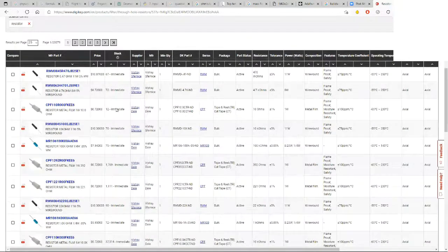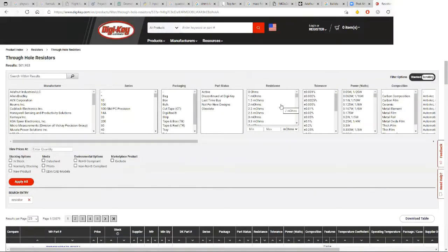Now, here we are. We have all sorts of resistors, but we don't need just any resistor. We want, let's say, a 1 kilo ohm resistor, or so we can type in this resistance box. What value of resistance are we interested in? We want something between 1 and 10 kilo ohms, so that we can power our LEDs from a 5-volt battery without burning them.